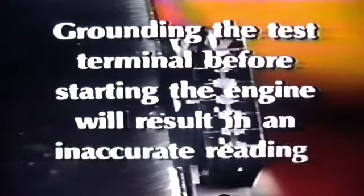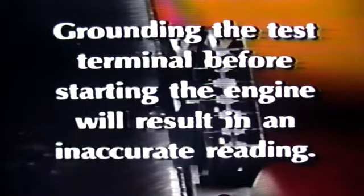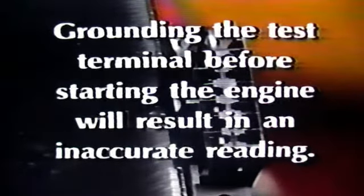Here's a good example of how one little mistake can blow the whole procedure. Following the check procedure chart, you'll first start the engine, then ground the test terminal. But if we ground the test terminal before starting the engine, we can forget about the rest of the steps because anything we do will result in an inaccurate reading. The right way to proceed is to start the engine, ground the test terminal, then disconnect and plug the canister purge system hose. For purposes of the test, we don't want fuel vapors running back into the system.